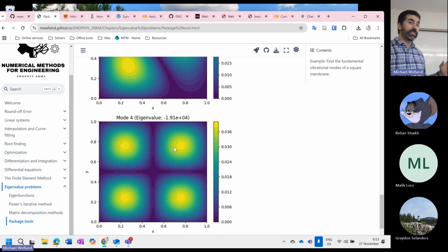So this particular problem, you can say that any vibration on a square surface has to be a weighted sum of its eigenmodes, which means you no longer have to solve the full problem. All you have to do is work out what those coefficients are. So this is the model reduction technique called proper orthogonal decomposition.